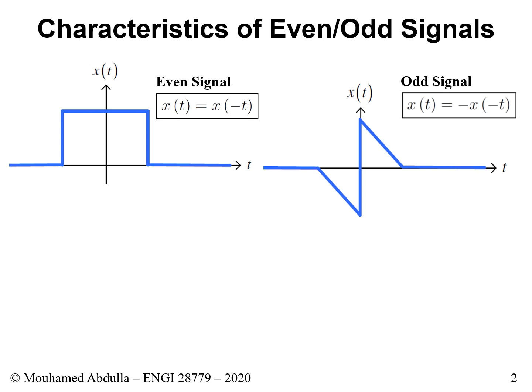The one that you see next to it is an odd signal. Essentially, what you have in an odd signal is that you have some pattern, and it has a specific symmetry with respect to the origin, whereas an even signal has a symmetry with respect to the amplitude axis, to this axis, right? Sometimes we refer to it as the y-axis. So whatever you see here, you see over there. Odd signal, whatever you see here, you see it on the other side flipped, right?